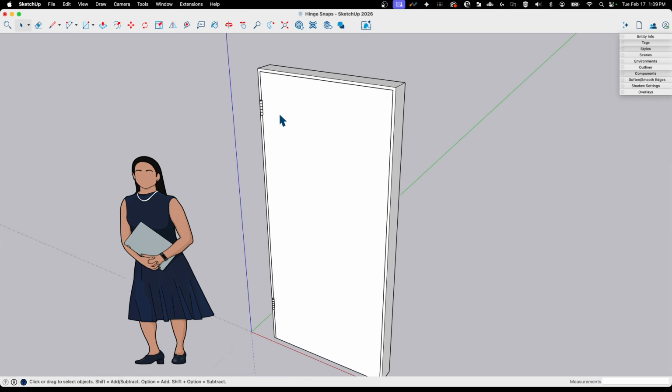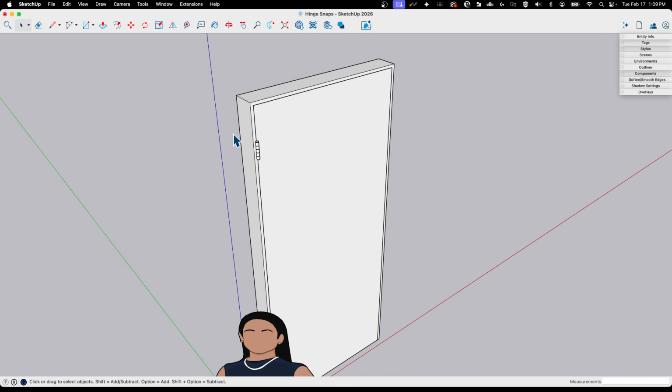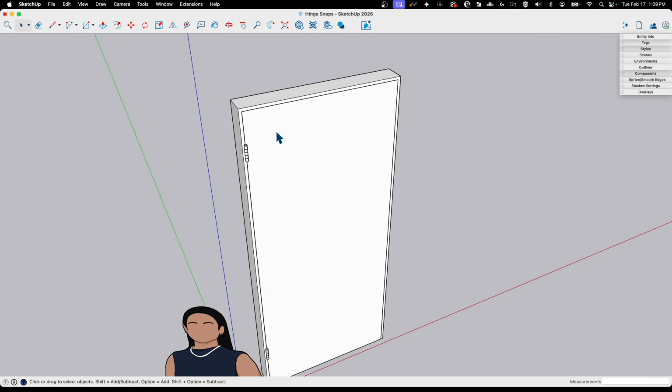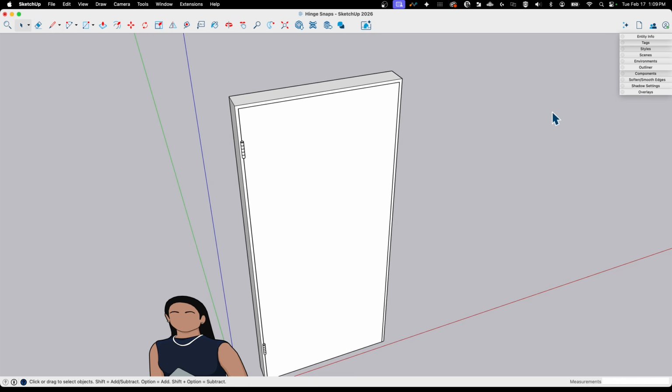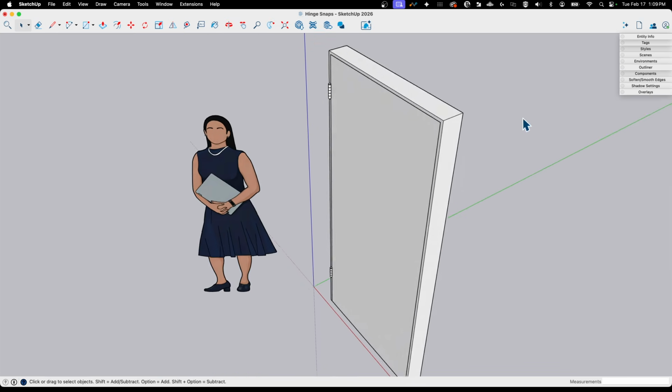And you notice I only did one snap too. If I wanted to, I could have done that earlier on. I could have taken this over here and modeled these two pieces separately and then put two snaps in the same place and snapped them together. That actually would have been more work than modeling it in place though. I only need really one snap if I'm using this as a handle to rotate, and that's on the geometry that is supposed to rotate when the door opens.